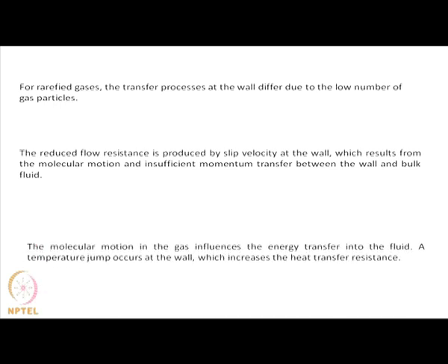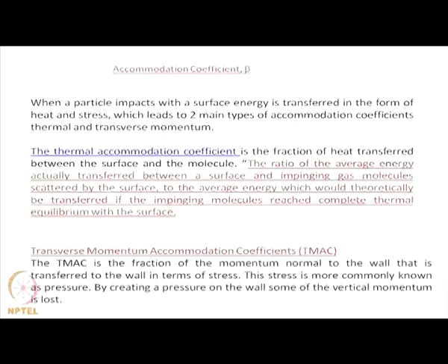So the flow is reduced, since we have a slip velocity, and therefore the flow resistance will be rather less. With the molecular motion, there is going to be insufficient momentum transfer between the wall and the bulk fluid. So in order to characterize the amount of momentum transfer and heat transfer, there is a concept